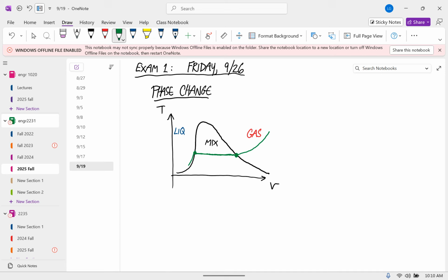So we have basically the liquid water is incompressible. No matter what its temperature is, it's basically just the same density. It's the density of water, which is what we're used to. Then it gets to that boiling point, and now the temperature isn't going up as you put more internal energy into it, but the volume is going up a lot because these molecules are separating from each other. And then once you get past that phase change, then you start getting an increase of temperature again, and the volume keeps going up.